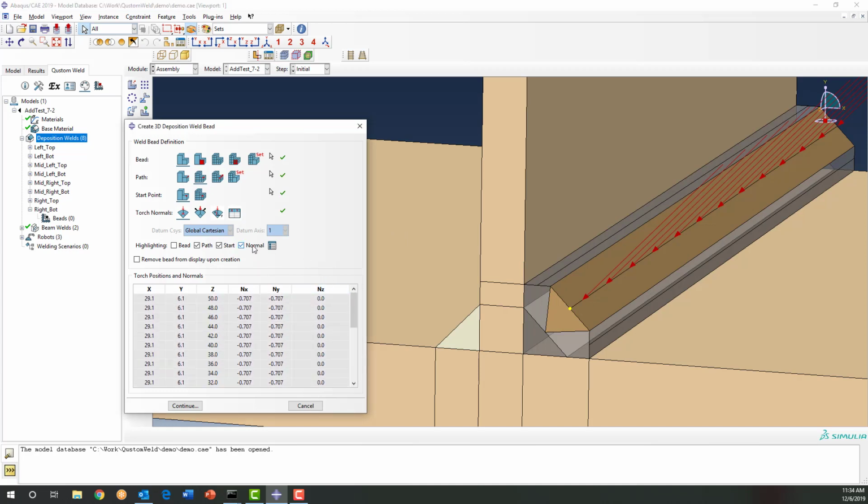So if we wanted to, we could actually modify the normals themselves, or read from a file somewhere and populate that and customize it. But normally this is going to be just fine. Now the other thing I want to do, since we're defining this bead first, and this bead is actually floating in midair, so when I'm done, I want to reverse the order. So just to make it easier to pick, I want to remove the beads as I'm defining them. And in the end, I'll just reverse them, and it'll make it easier to define the beads.